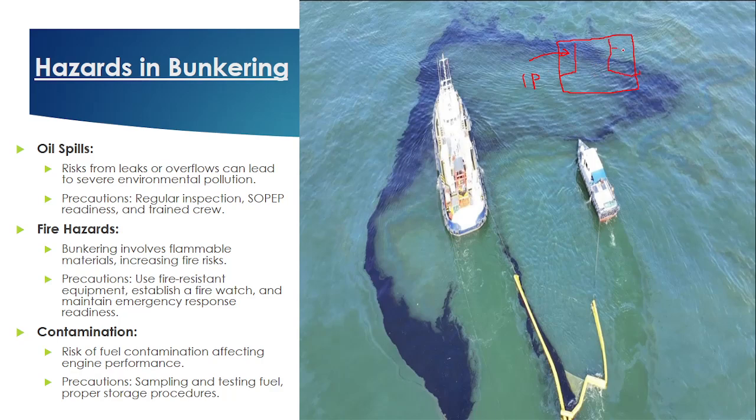In one starboard there is some fuel. Okay, there is some fuel in the one starboard, and you don't need to take any bunker in one starboard, but because the bunker valve is leaking, some oil got transferred here also. This type of contamination can only be avoided if you are taking proper sounding of all tanks from time to time throughout the bunkering operation.